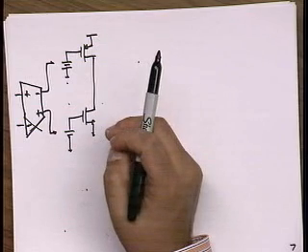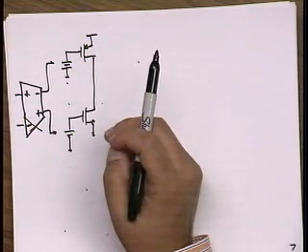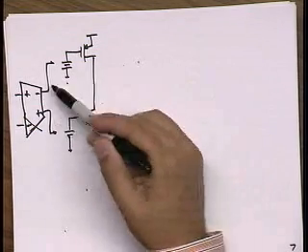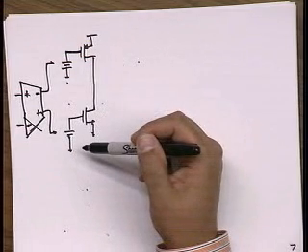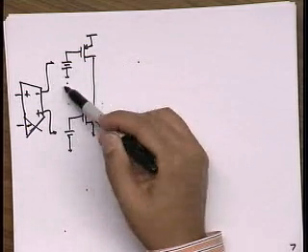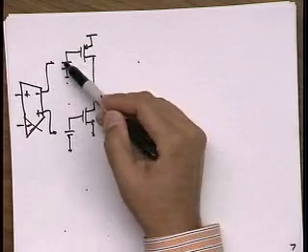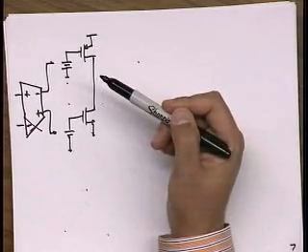If it's DC, then the output signal is 0. Well, let's say AC, right? What's going to happen to the AC signal coming out of here? To the ground. Yeah, it's just shorted to ground, right? It's not going to be able to develop a voltage to drive these stages.